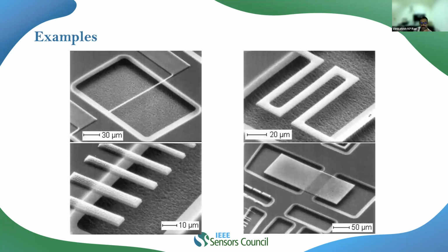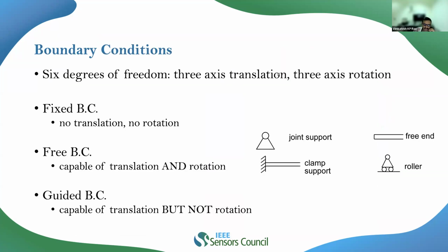So these are the microfabricated structures what we can see. This is basically a fixed beam. This one can be realized quite easily using your SOI process also. And these are basically cantilever beams, which again can be realized with your SOI process. This is again a cantilever plate. This also can be realized with whatever process we will be following. And I was telling you in the earlier case, if you want a larger length of the beam, then we indeed go forward for serpentine beams. You can even realize the serpentine structures with the help of SOI process.